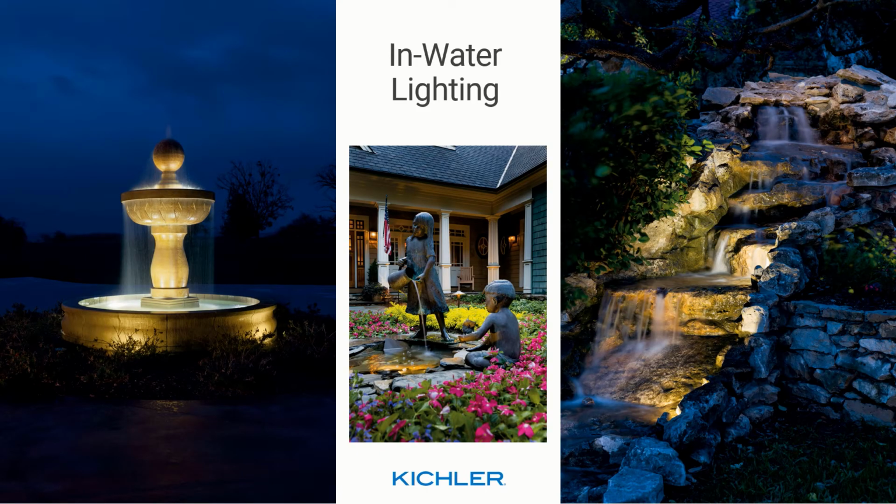Low-voltage lighting is not approved for use in bodies of water where a human intends to bathe. Fountains, ponds, and falls can benefit from good lighting, but watertight construction is required for in-water illumination. Wire connections must be made on dry ground, so longer wire lengths are required. High-quality, rust-resistant, and fully sealed products make this a very specific specialty product.